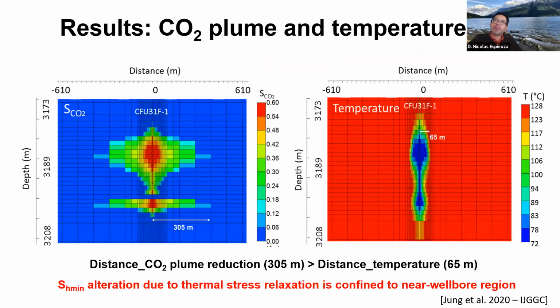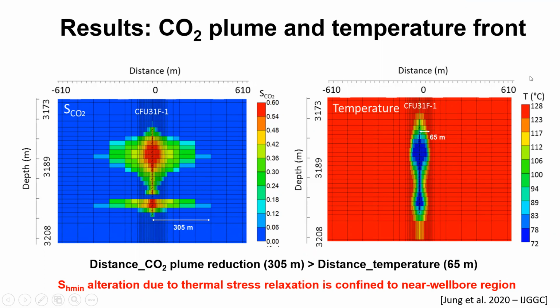Okay, well, the problem is also related to the injection rate, because eventually, if you inject slow enough, the fluid is going to draw heat from adjacent rocks, and the temperature is not going to change that much. I would say mainly the problem would be when you have high injection rates and your temperature changes very quickly around the injector. Yes, thanks. Okay.